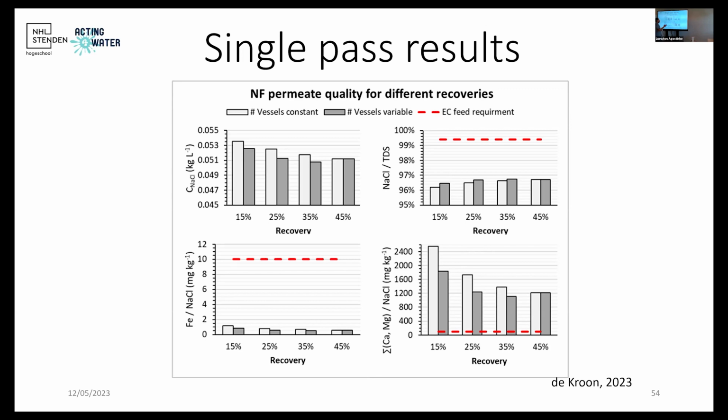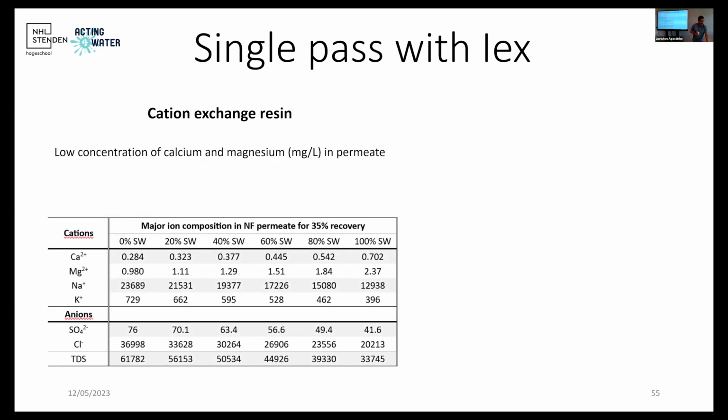So you decrease a little bit your total concentration, but the total volume of the plant is more than enough to have lower ranges here and still have the production demand that the plant needs. But this is critical. This is very critical because this will decrease drastically the lifetime of the electrochlorination system.